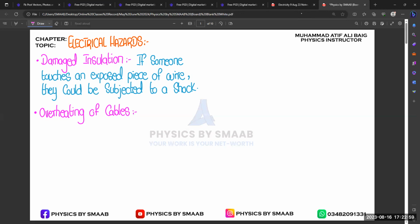That's why we always connect a refrigerator or microwave oven with the main supply. We don't connect those wires with the extension wire. If we are connecting them with an extension wire, that extension wire should be of excellent quality, with excellent insulation, right? Then we are able to use that one, because we know that if we increase the length, your resistance automatically increases. So when resistance increases, your temperature increases, and that will be the same factor, overheating of cables, right?